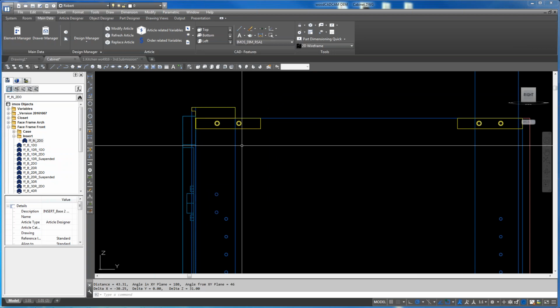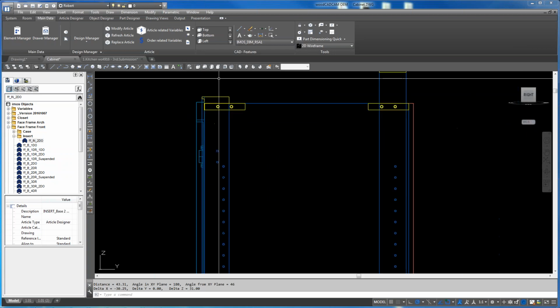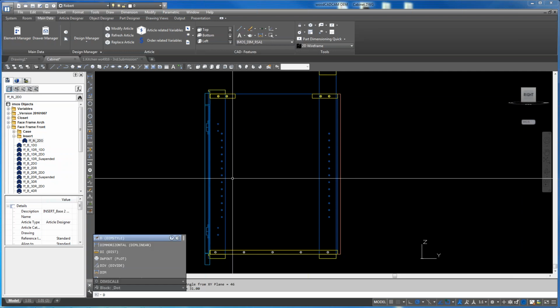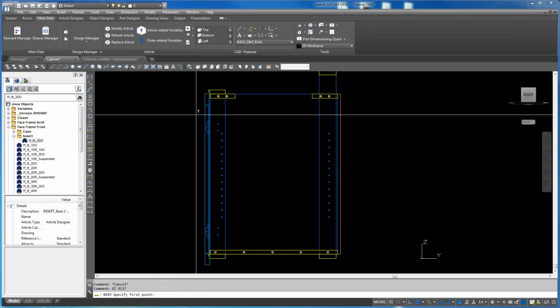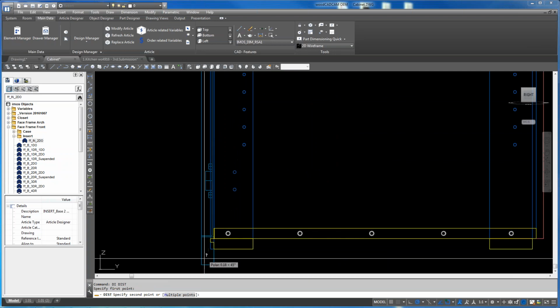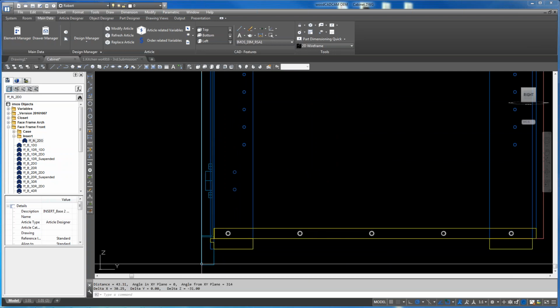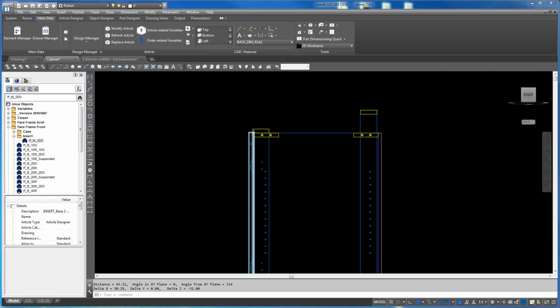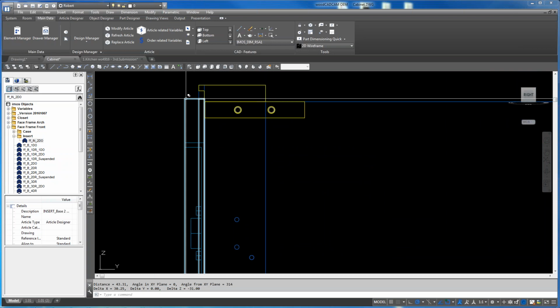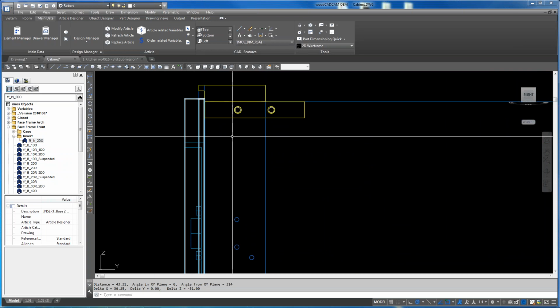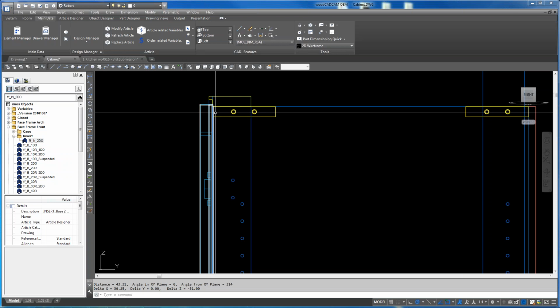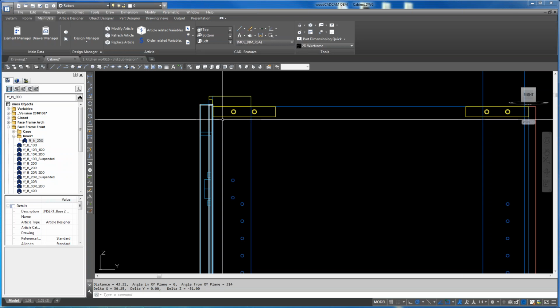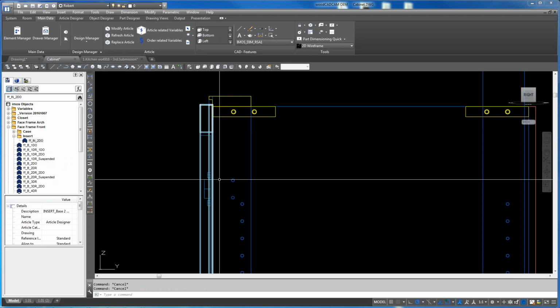It's 31 inches, from top of the frame to the bottom, and that should be 30 and a half, right? Yeah. At 30 and a half height, that's the box. If you check from the outside of the blocking of the filler, that's the 30 and a half. So right now my frame is 31 inches. The frame should be 30 and a half.